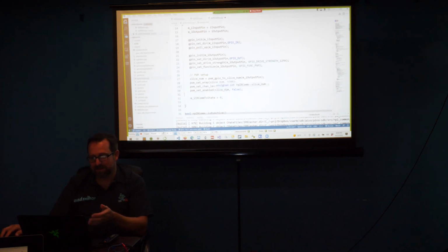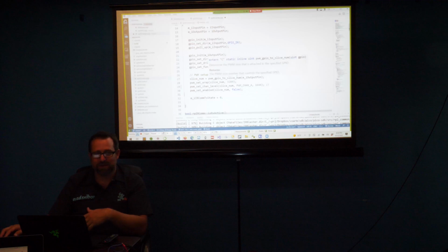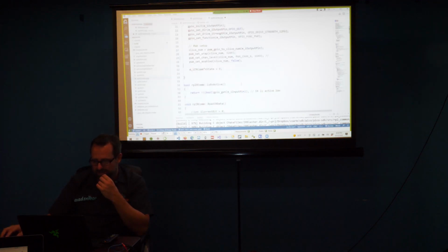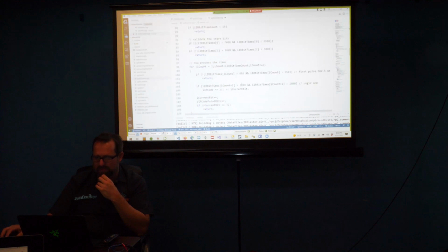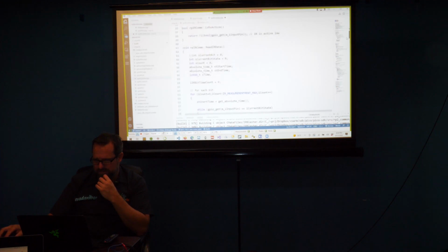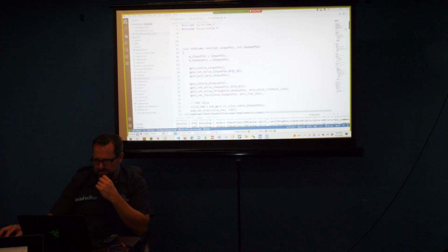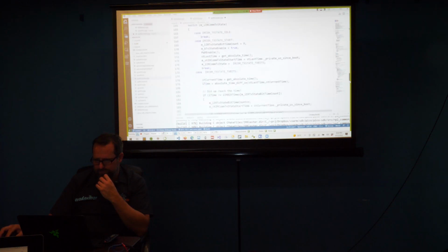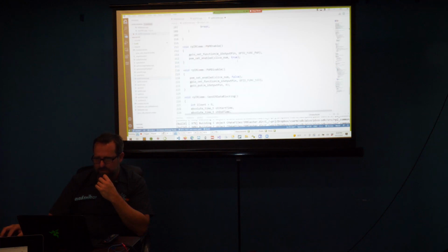All right, so that's the setup. Once the PWM is set up, you just turn it on, and you generate that square wave whenever it's on. So coming back to the enable, it's as simple as telling the GPIO you're going to use PWM, and then you turn it on.